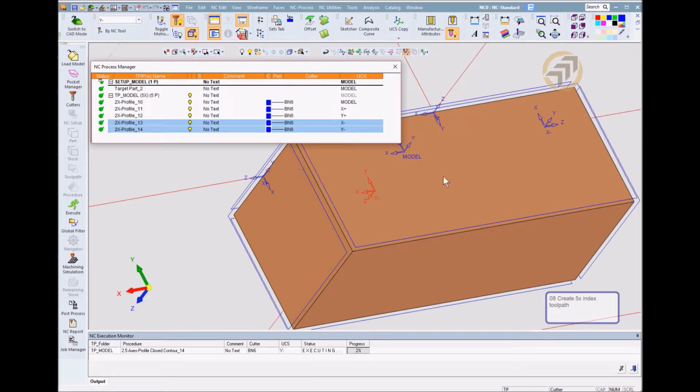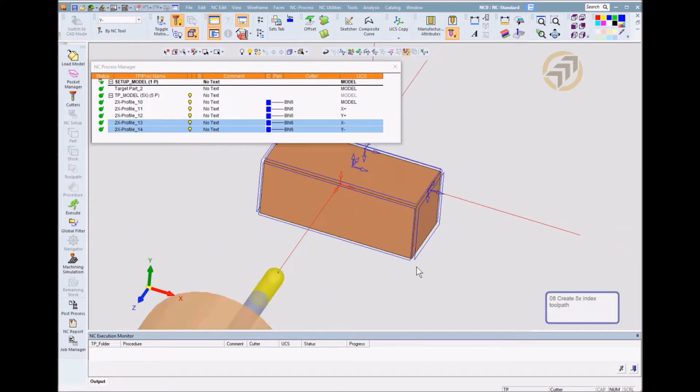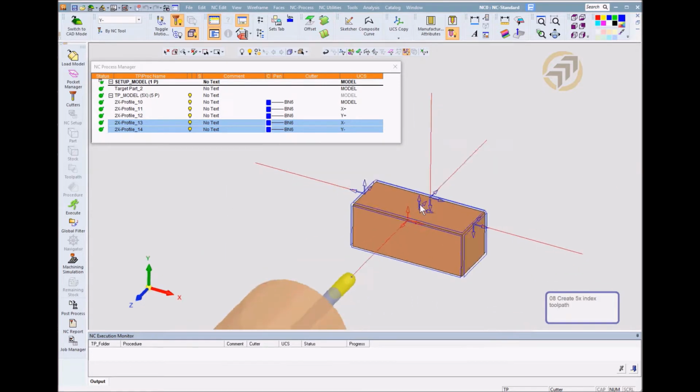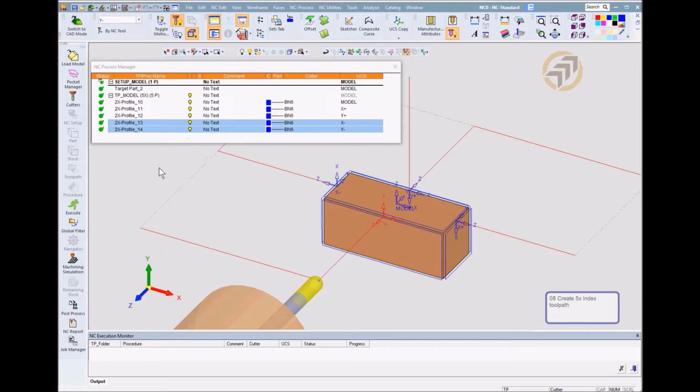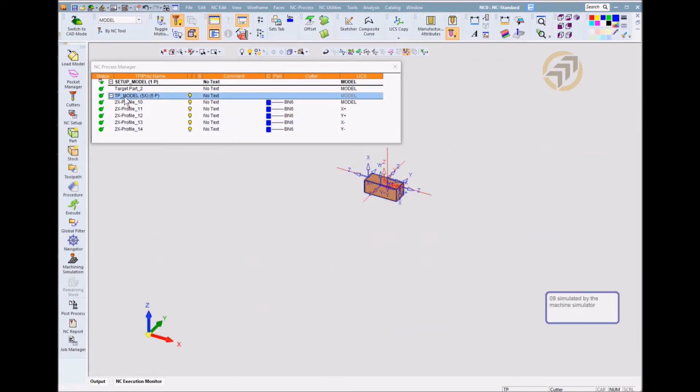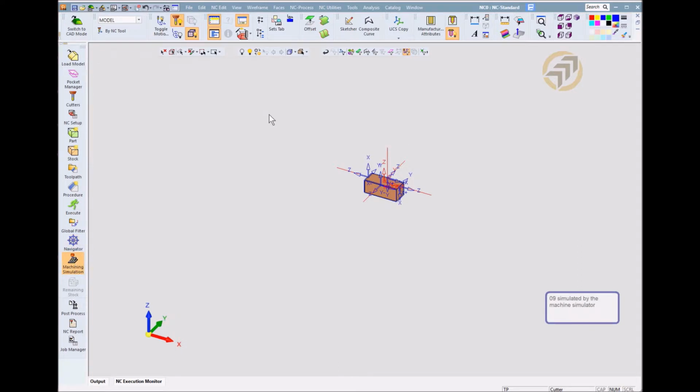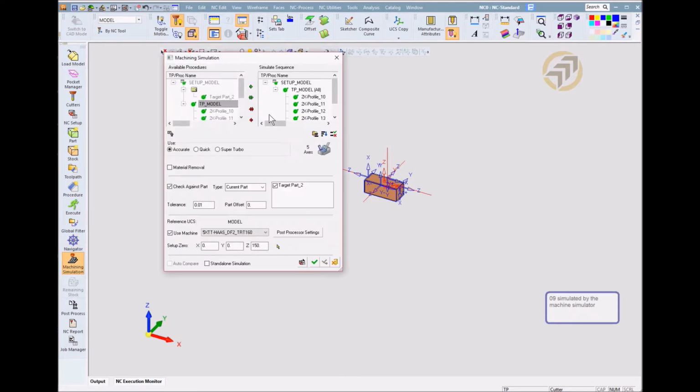Right, so then this is all the profile toolpath that we needed to test the movement. Save profile. Next, let's check the machine simulator to see if our machine is set up properly or not. Yeah, and click OK.